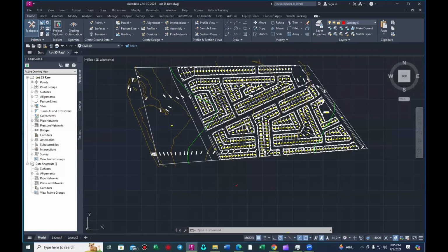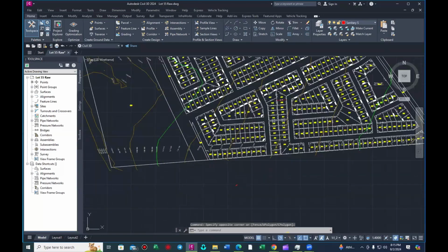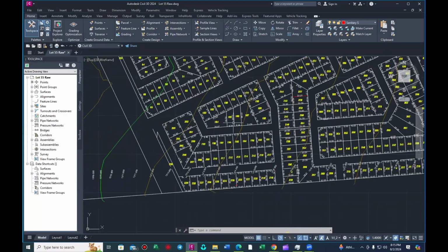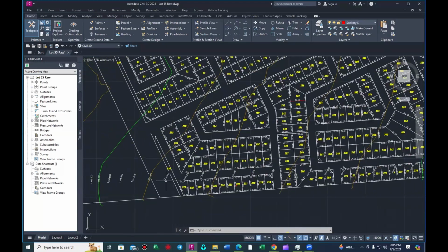Anyway, so this is a mid-block section that I was talking about, right? You're given this stance here that you guys are seeing. I'm not going to do surface analysis. The surface was already created. One thing that I wanted to show you is where my sewer is going. So quickly I do what I call the quick profile tool. I go to my polyline. First of all, I create a layer for the sanitary sewer. As you can see, I created a layer there.